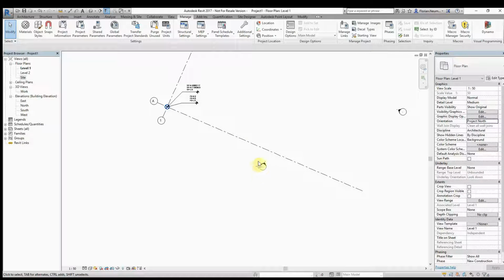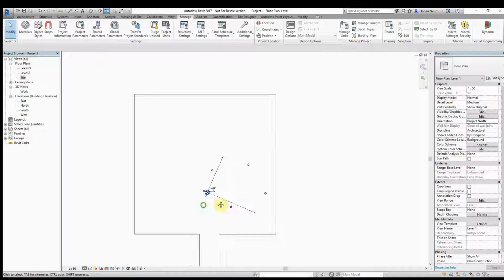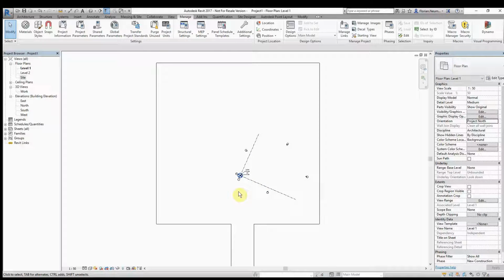Probably I just need to set up my elevations again here in my project, but it doesn't matter because I do this once in my life for this project and never again. Good, and so having these, for instance, here around, or I rotate this whole project. Ideally, when you rotate a project, theoretically, I would say around the survey point, it's probably the easiest.